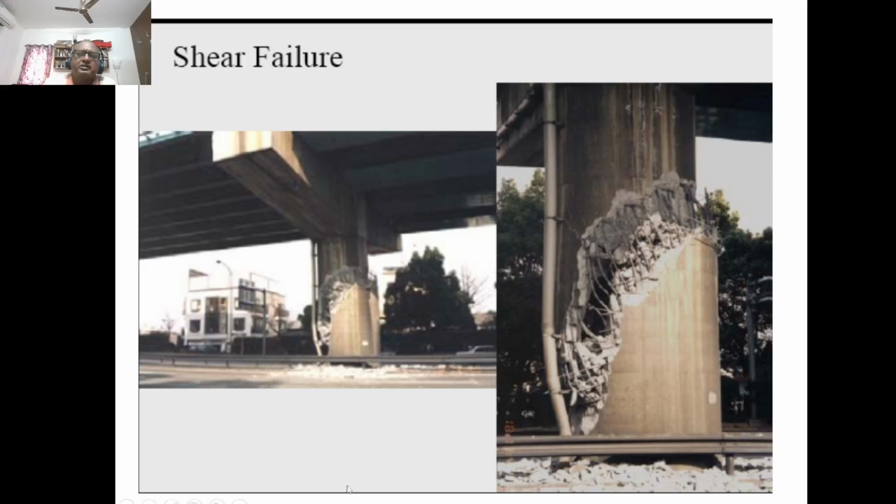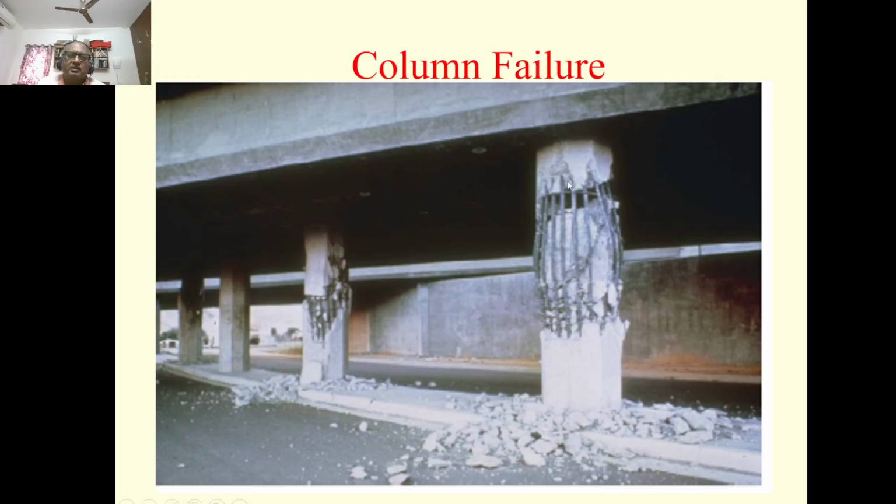Depending upon the stiffness and delta, the shear force, or lateral force as the case may be, is not sufficiently catered for, leading to this failure. So one has to take care of this kind of shear failure. Most of the failures are in shear, not like a frame system where we see bending moment failure. In a pier system, it is shear failure. This is also a column shear failure.